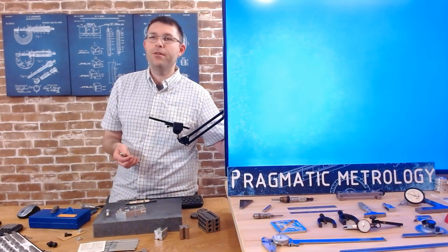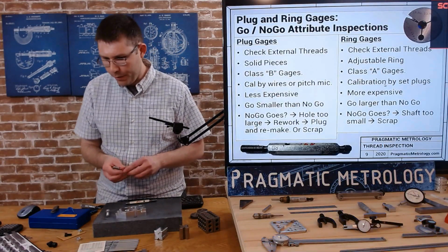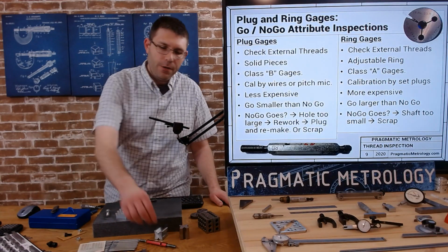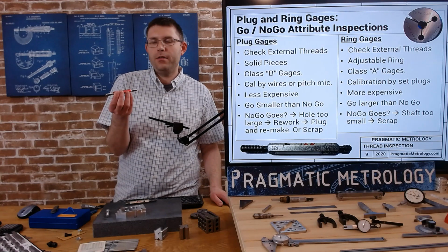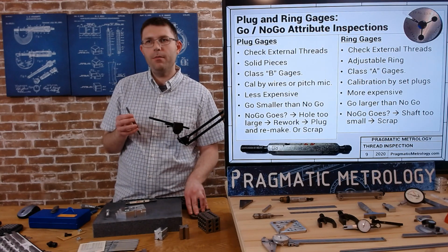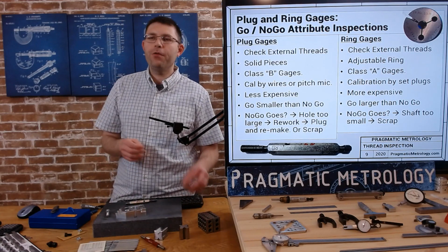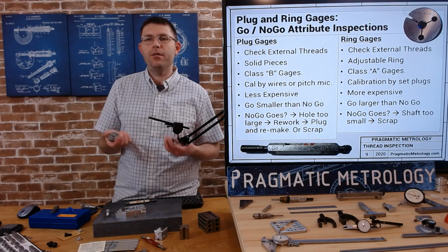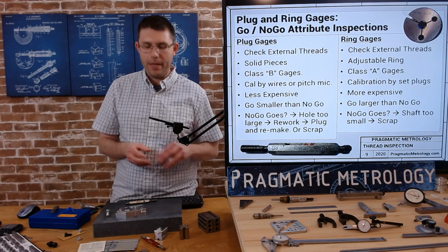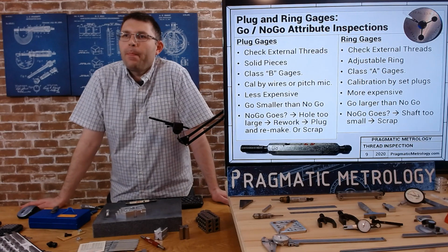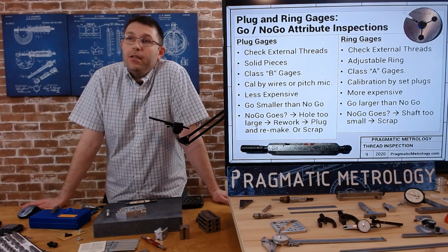External companies are actually usually preferred to internal calibrations. For one thing, you've got to get these set plugs calibrated, so you might as well just send the rings out for calibration. And calibrating ring gauges takes a little practice, and the calibration companies have that experience, and not everybody who works with ring gauges does. Generally speaking, let's move on.